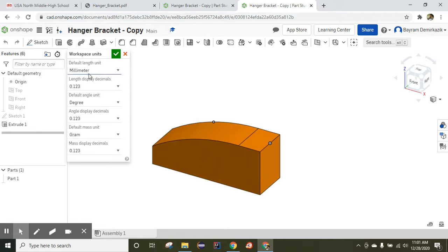Okay, now these two parts that are touching each other, it's too sharp, so we need to use the fillet tool. I'm gonna use this fillet on the sketch. If you don't have this, you can press Shift F, or you can find it from the search tool. You just need to type fillet, and you will see the sketch fillet here.